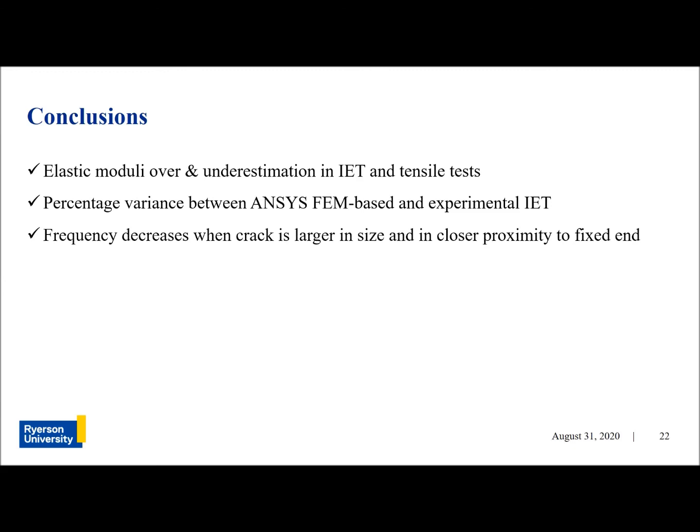Using experimental and FEM analysis of the effects of through-thickness cracks on the vibration response of a defective PLA beam, the general trend showed that as the size of the crack increases, the fundamental frequency decreases. In addition, a doubly cracked specimen exhibited a lower frequency when compared to a singly cracked one with a similar defect size.